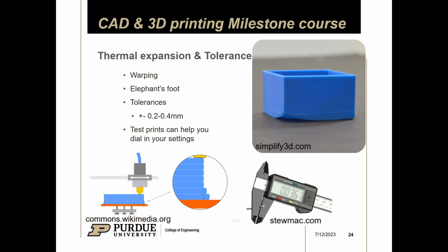That can be strong enough that it lifts from the corners of your parts. The way to mitigate that is to reduce the number of sharp corners, because sharp corners create a stress concentration. In this case, they printed a cube and the corner is where all the stress was, and it pulled so hard that when it cooled, it lifted.